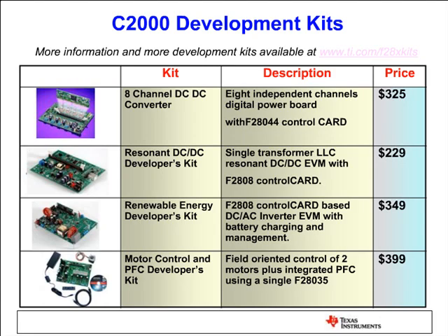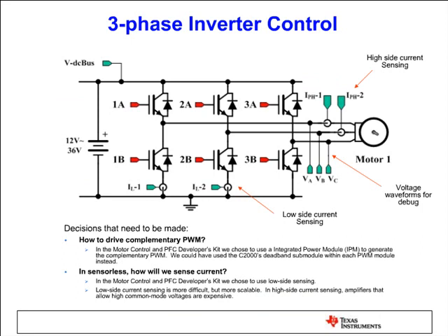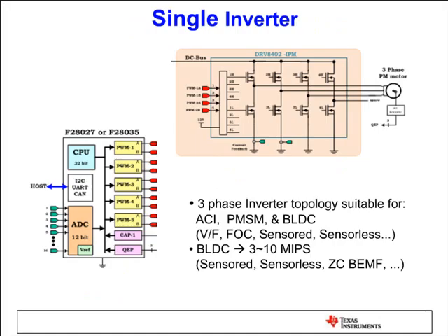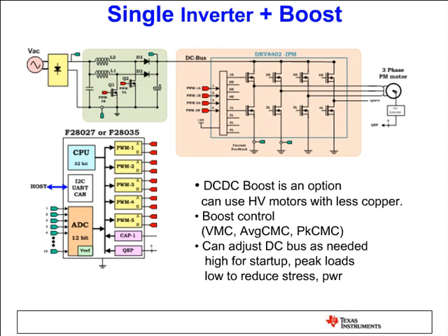I'm going to talk about the dual axis motor board we recently released, 2 motors plus PFC. So what we did, we prepared a platform both for Piccolo A and Piccolo B, and this is a motor control platform that people can experiment with, like single motor control, or PFC plus single motor control. We have a front end PFC stage which controls the power factor, boosts the DC bus voltage, and keeps it stabilized.